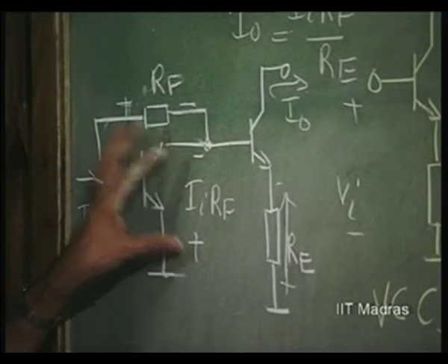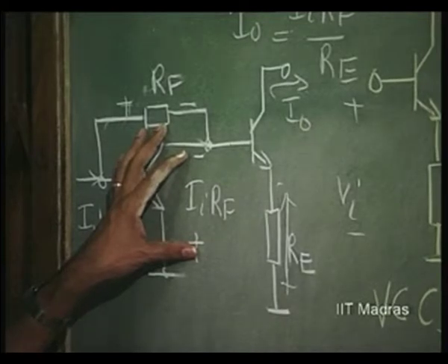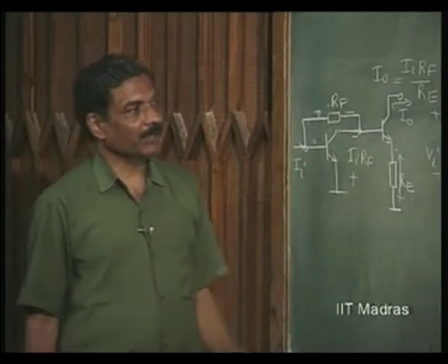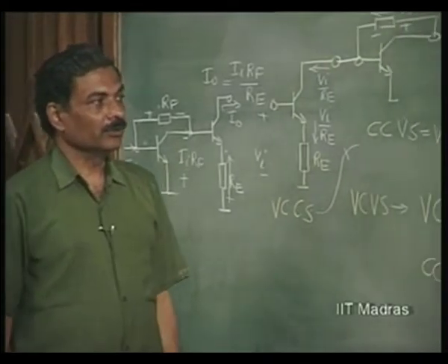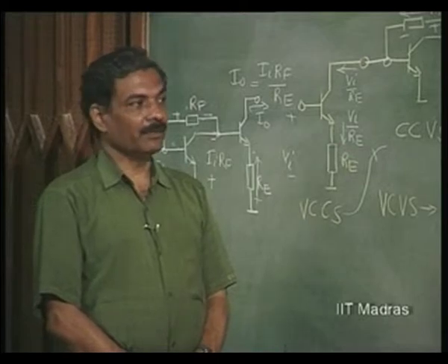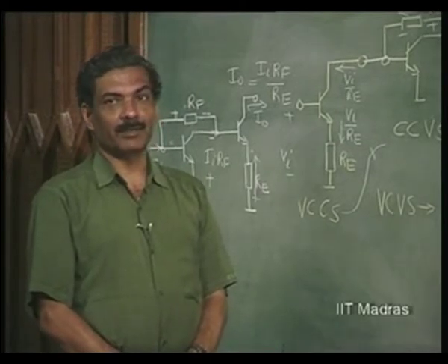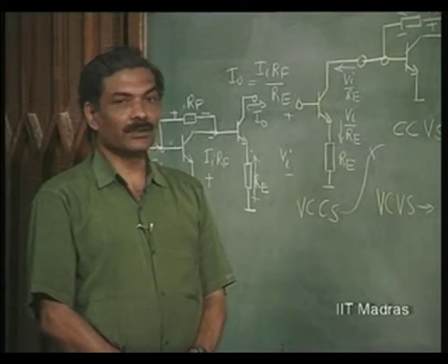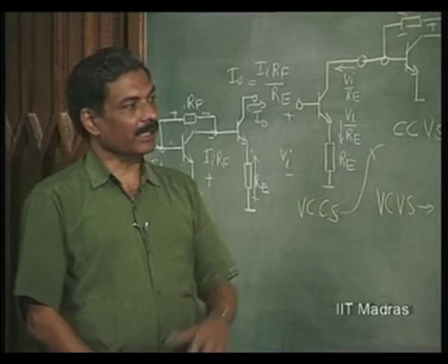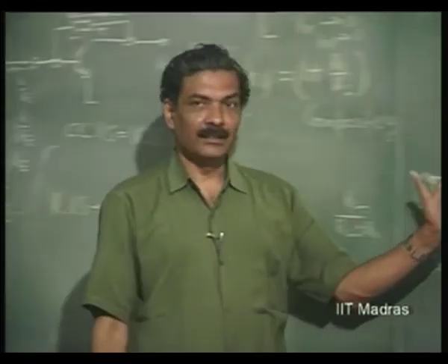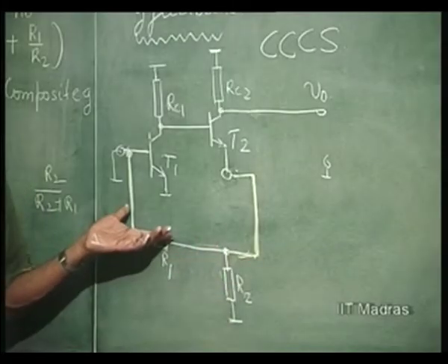but we will later see that there is a great advantage in local feedback in terms of trouble free operation at high frequencies, because as you increase the number of stages, we get into the problem of oscillations. Negative feedback turns itself into positive feedback beyond a certain frequency, and the circuit, instead of amplifying, is going to oscillate. This we will later on discuss. So, it is not always advantageous to simply cascade amplifiers and then give overall negative feedback.